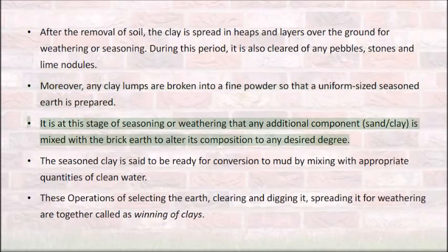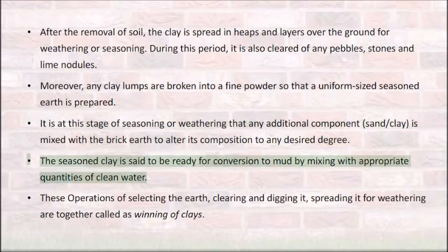It is at this stage of seasoning or weathering that any additional component, sand, clay, is mixed with the brick earth to alter its composition to any desired degree. The seasoned clay is said to be ready for conversion to mud by mixing with appropriate quantities of clean water.